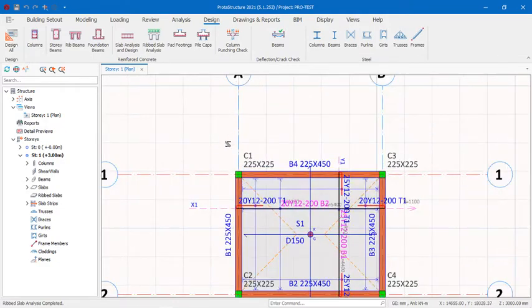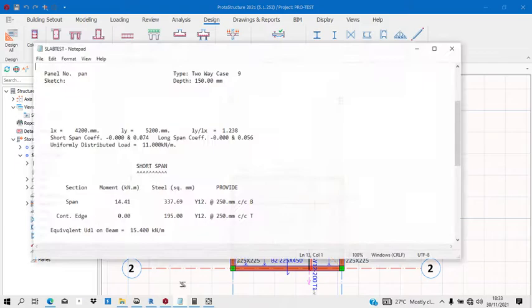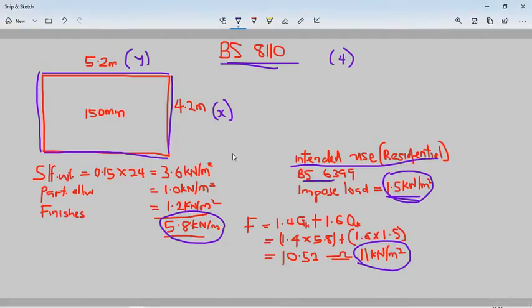We have to probe, because the thing is that we idealize structure as civil engineers. And when we idealize structure, we are saying that we are predicting that our structure will behave in a certain way. That's the purpose of idealization. So when we idealize, if I idealize something like this, which I'm saying is simply supported, my movement will be like this. It will be zero here, it will be zero here, then I will have my maximum movement at the mid span.